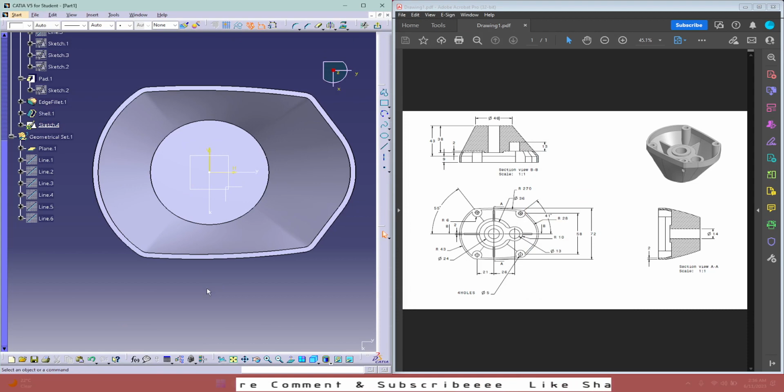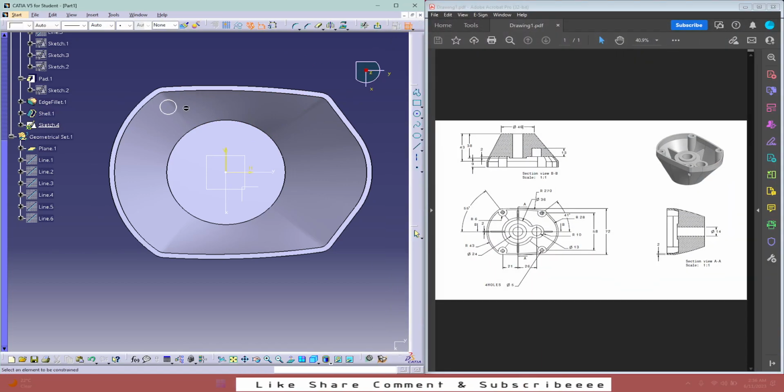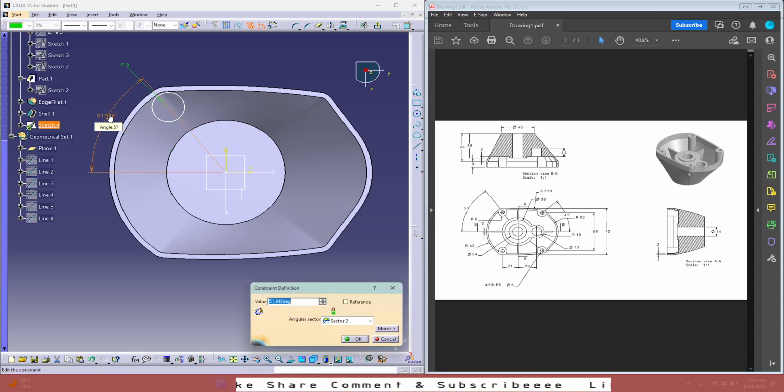And now I'm going to take a circle profile like this, give it a dimension, 6 radius, and we are also going to need an axis, so connect the center point and then give this axis an angle of 55 degrees.